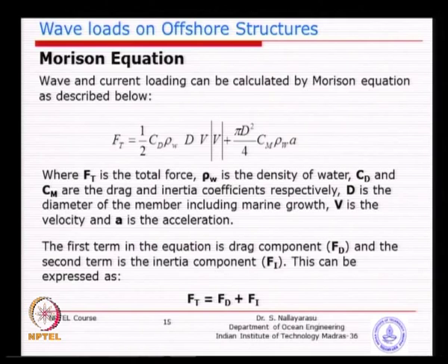This is basically for a pipe, that is what I have written here. For other forms you will find the formula different. Here I am just using a circular section, like we mostly use for jacket type structures. So, pi d square by 4 is the area multiplied by unit length, that is not given here.